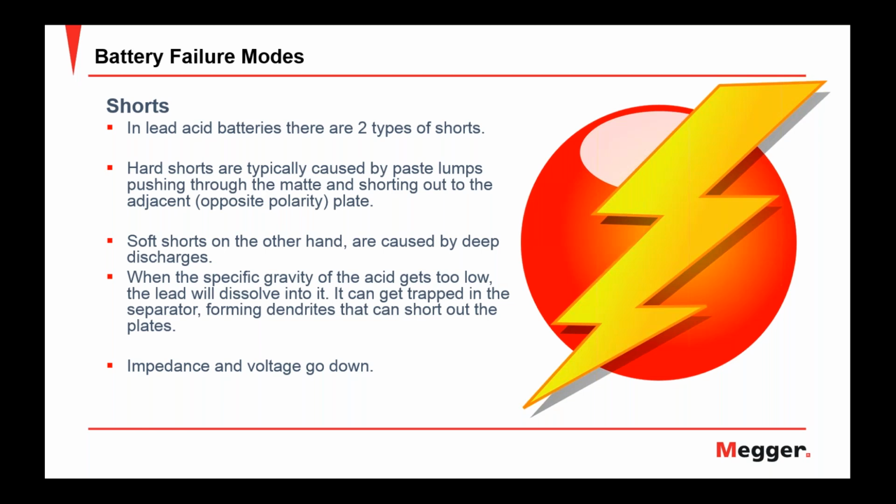We all hear about lithium-ion batteries. Every time there's a fire with a lithium-ion battery, it's reported. But in truth be said, the batteries that have the most fires are car batteries, because people don't replace them when they die. They just keep trying to use them. So really, if you do have a car battery and it drops, get it jumped, get to where you're going, but replace the battery. And I'm talking about car batteries here, but this is not specific to that.